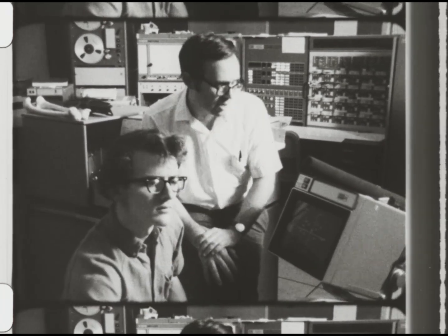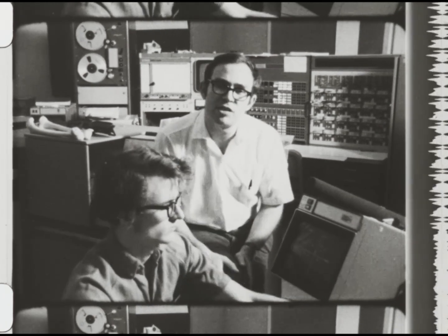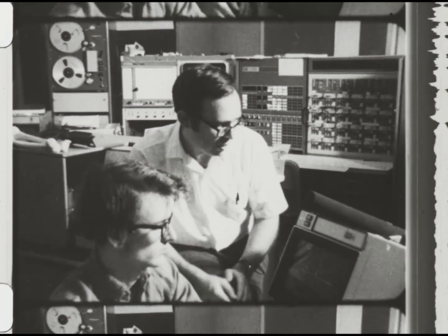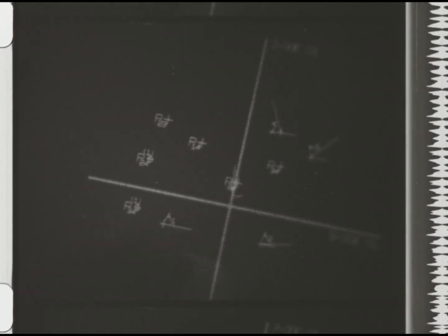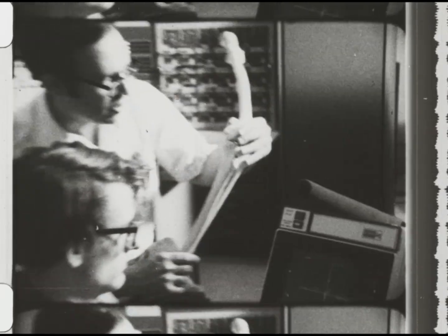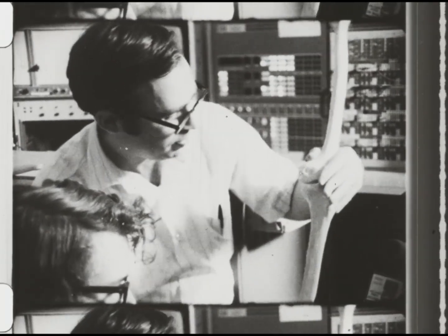So the problem in designing a knee joint is that there isn't a simple, single, fixed turning joint associated with all the positions that the knee bends through. But there's a combination of a sliding motion and a rotating motion that takes place in the joint.